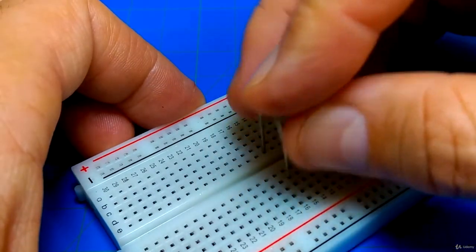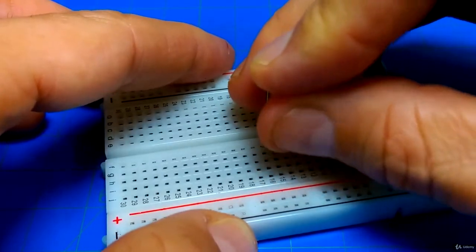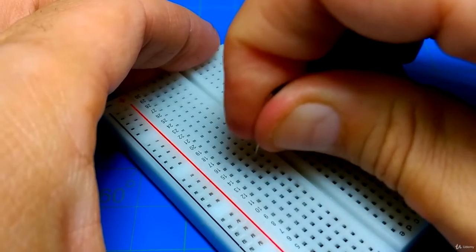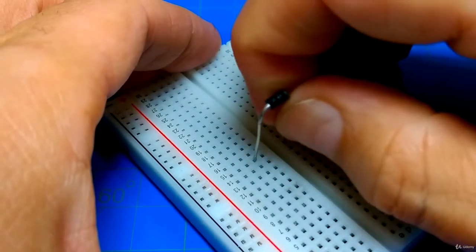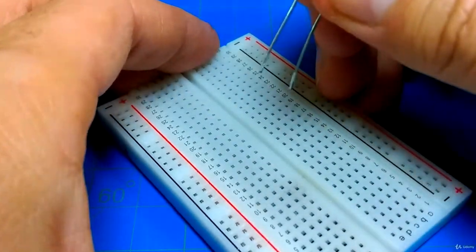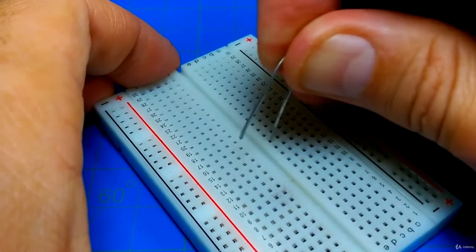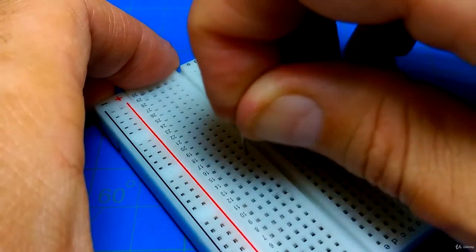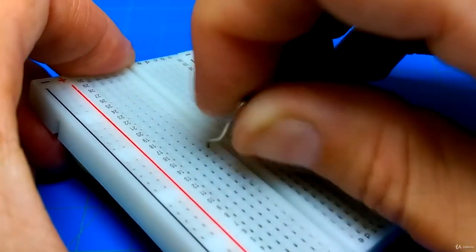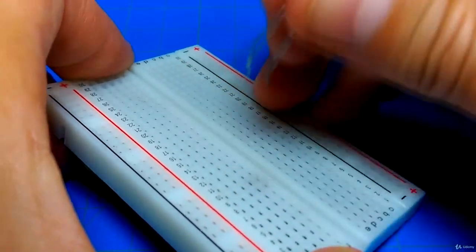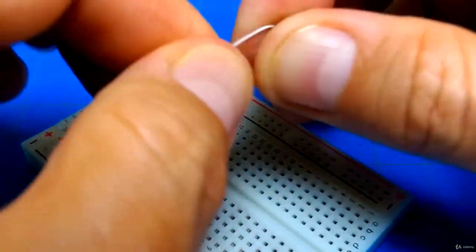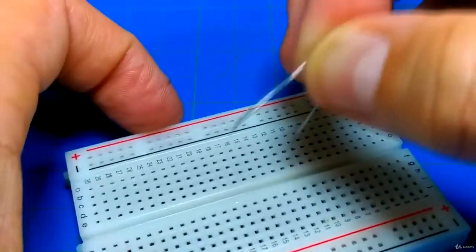And again, do it like you mean it. I'm pushing it, not too hard, wiggling it, rolling it around, working it in, and it's not very easy. Right there, it's really binding, right? So that's not making me happy, and I'm probably messing the board up a little bit. Again, I'm trying to get the camera angle so you can see it. And oh, see, it bent. So right now, this is telling me, hey, you need to really chamfer these a little bit and clean these ends up so you can push them in here without damaging this board.